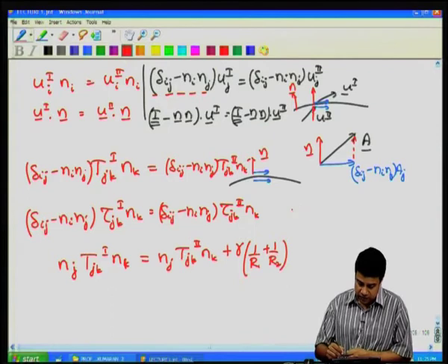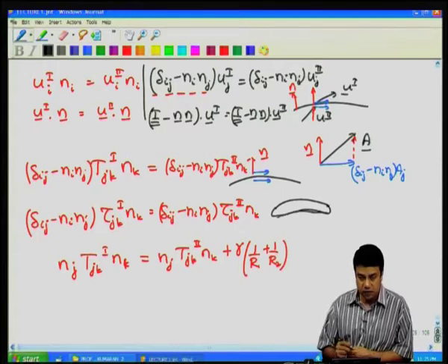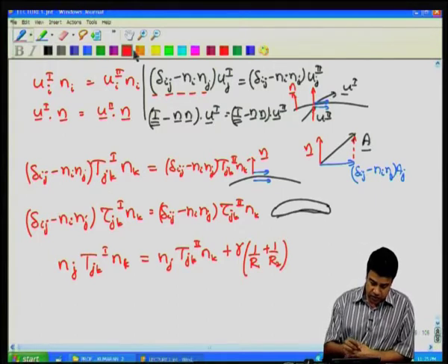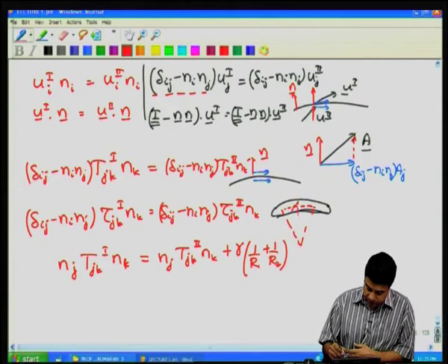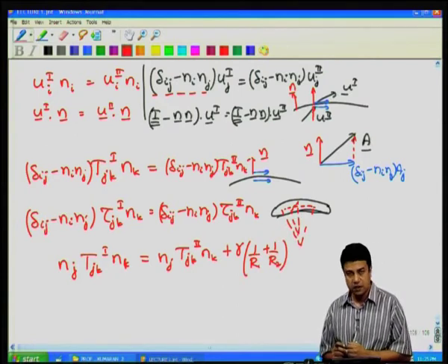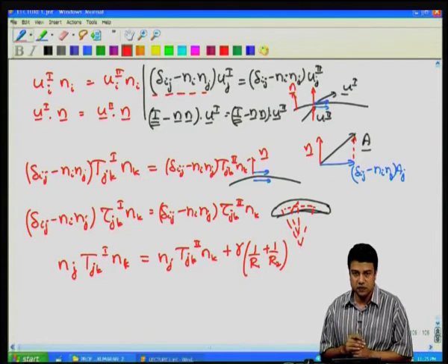So, if I have a curved surface that looks something like this, I will have two directions along which the radii of curvature are either maximum or minimum, and these are two perpendicular directions. Along those two directions, if you calculate 1/R1 plus 1/R2, that times the surface tension coefficient gives me the difference in the stress between the two fluids.